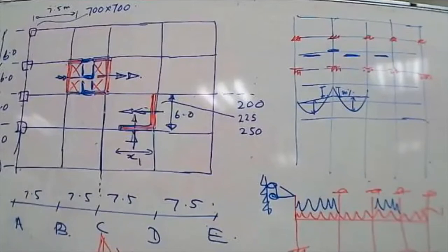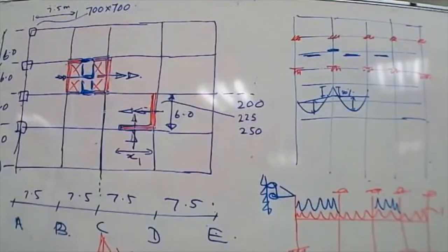And another thing, sir, when we design for the span, are we going to consider the flange section to design a span? Or if we use a rectangular section design, do we still need to provide additional reinforcement? No, I would always go with a flange beam design for the span because it's very economical. I will not design the span section as a rectangular section because it's going to behave as a flange beam. I will always design it as a flange beam. Is that clear? Clear, sir.